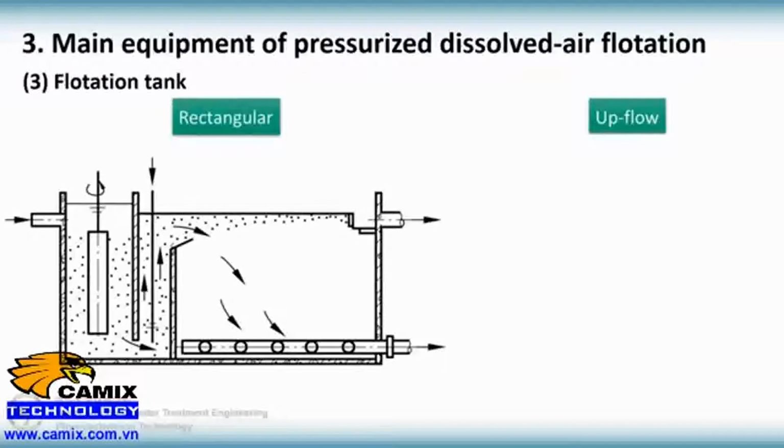After coagulation, raw water enters the flotation tank mixed with air dissolved water and solid liquid separation happens. Here we address that scum is discharged from the top of the tank and treated water is discharged from the lower part of it, which is different from the sedimentation tank.